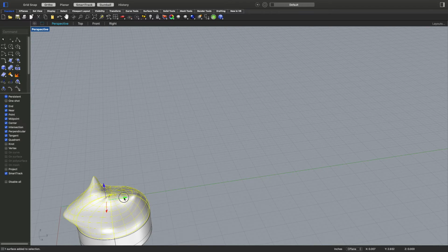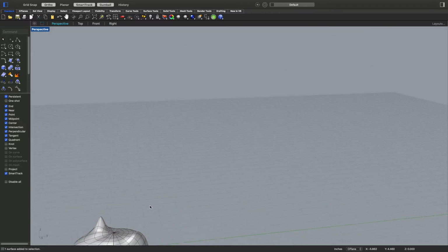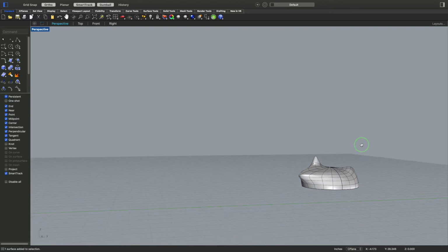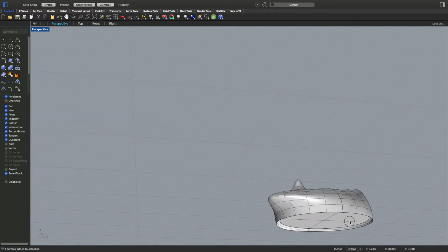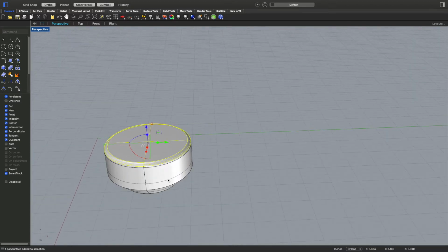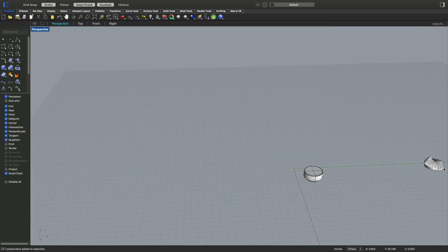And now what I've got is a shape that I can move back over here 20, and it lines up with that perfectly. That's why I'm moving it by 20. So I should be able to join these two together to make one piece. That'll be my lid. And then I'm going to join this back together. So just join, J-O-I-N, or the puzzle pieces. And then I can move this back -20.